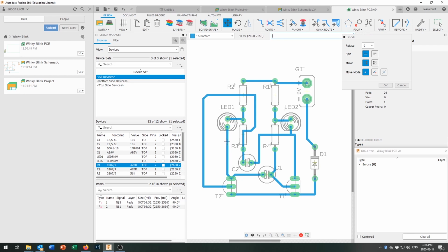Now the nice thing is that if we decide to print out onto the top side of the board, you don't have to worry about whether those are over top of a copper line or not, because that copper line is on the bottom side of the board, and anything that prints out here will be on the top side of the board, and you'll have a very opaque board in between. So you could put that right there in the interest of us having lots of space and making it easy to read when everything's on there. Oh, right down there looks like a wonderful spot.